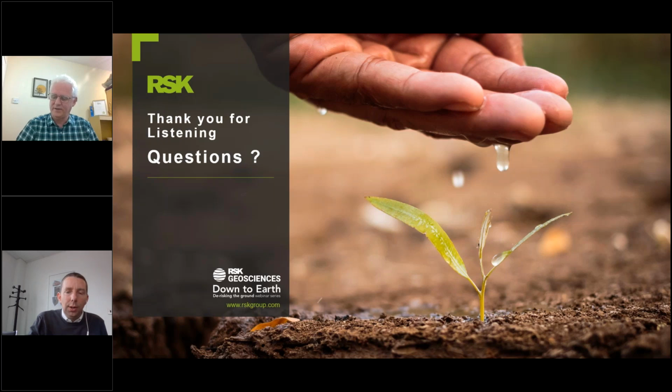I tend to agree. I think you would find very quickly whether or not the soil seemed to be close to its recognised natural moisture content, or whether it had been significantly affected by desiccation. So it would give you a very immediate alert to the fact, yes, you're going to have problems, or it could give you a bit of confidence that it looks to be about the right moisture range. So that could give reassurance, I suppose, and it could help set costs a bit quicker.